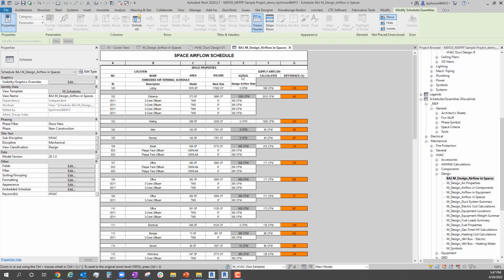Because what I'm really wanting to do is get my actual and my calculated to balance very easily. So to also figure out what those should be, I kind of need Revit to tell me what those values should be, right? I know based on these two numbers that these should be like 500s, right? And I may just leave them 500s, but there's a little bit more than 500. So what's the actual value that I'm looking for? So in this case, I'm going to go back to my filters on my embedded schedule. Nope, which one?